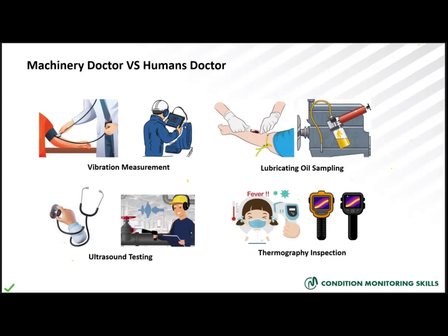The role of a machinery condition monitoring specialist is very similar to the human doctor role. Both are using suitable tools to diagnose and monitor the condition of what they take care of. If I'm taking care of this machine, I'm going to measure the vibration, check the ultrasound, take an oil sampling, do a thermography inspection, and so on.